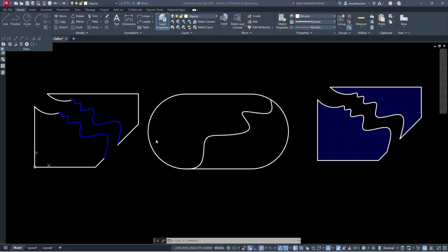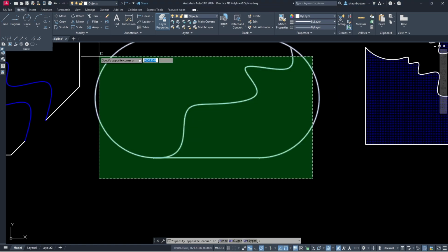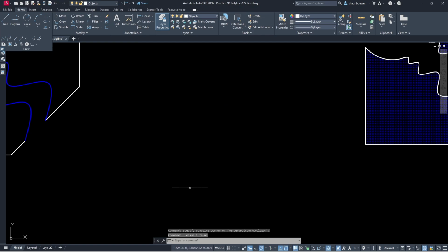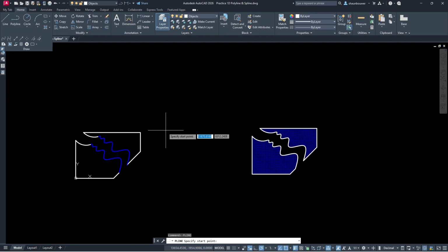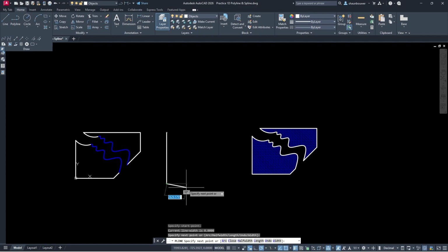Next, here is a demonstration. If you want to create a shape like the one there in the middle, you can use your polyline command or type in with the dynamic input your p-line command. Then you can start with the Cartesian workspace. You can input your information for the exact starting point if you want to use the coordinates, or for this example, I'll just freely draw.